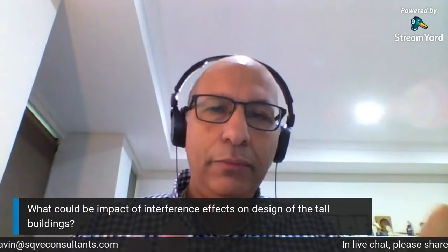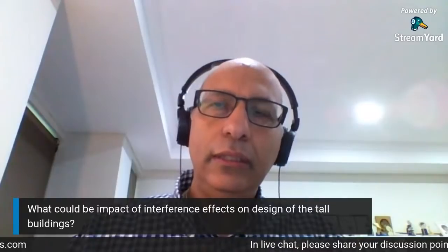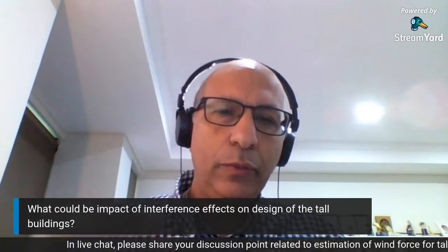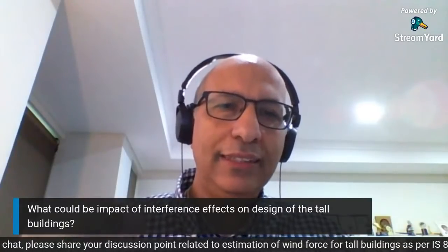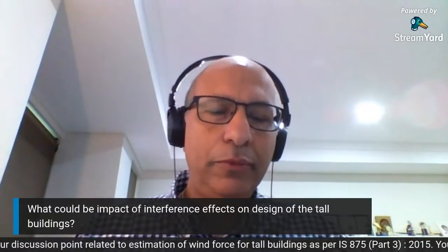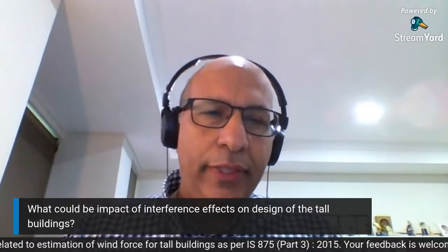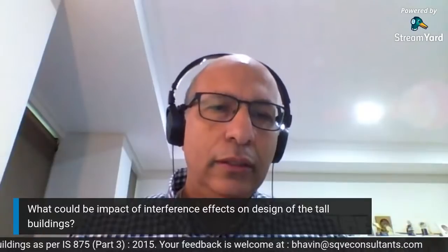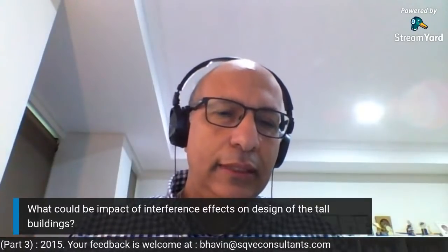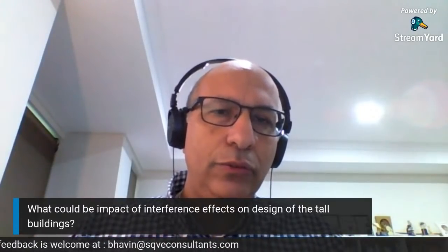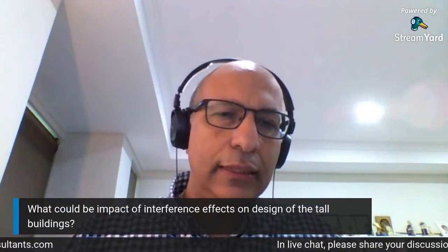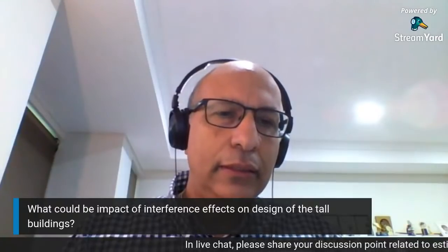As a rule of thumb, the widths of the two buildings need to be similar for this to have maximum effect, and the shape obviously similar, both rectangular. Also the distance is roughly between 4 to 6 or 7 building widths apart.